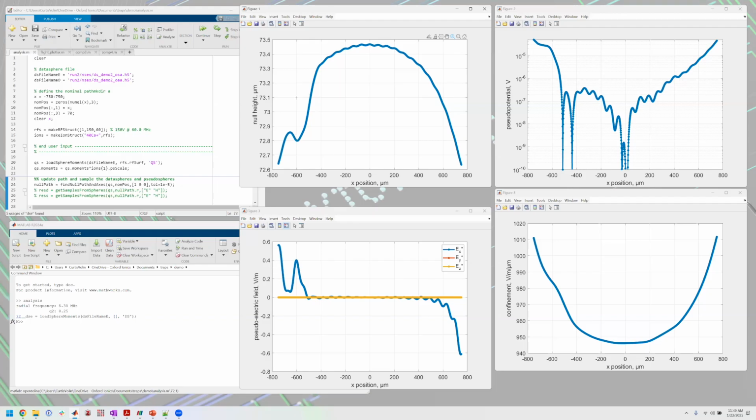And in fact, I think this is a key difference between what you would see, for instance, using a gapless approximation and trying to simulate a load hole or a hole in your trap, versus what Nullspace is giving you. You see that in reality, because there's no ground plane underneath that portion of the trap, the ion height drops. If in the gapless approximation you just fill that with ground, you would actually have the opposite sign. You would have a bump up in the simulation because the RF rails are ever so slightly further apart in that area.